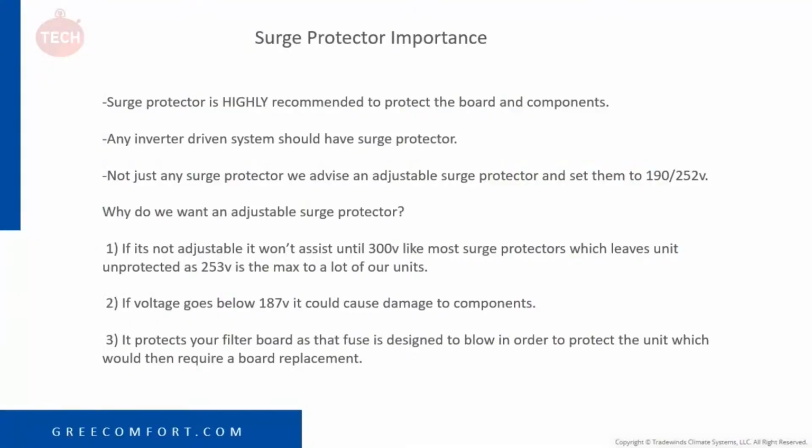All right, now let's go over the importance of the surge protector. Surge protectors are highly recommended just to protect every component on this inverter driven system, from your compressor to your condenser fan to your EEV. Anything that's controlled by DC voltage is highly susceptible to power surges. So that's why we want to have a good surge protector on there.